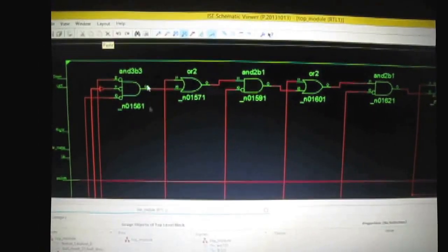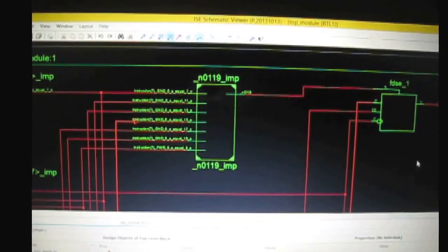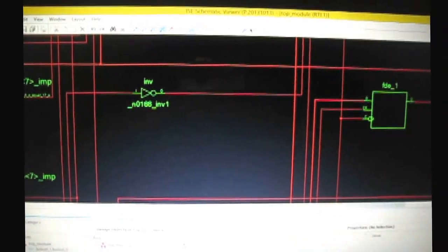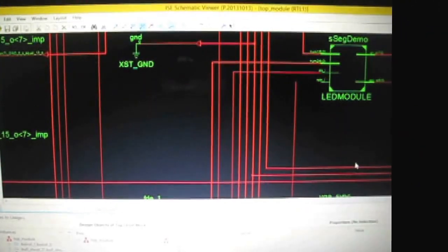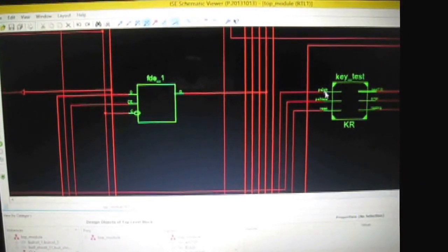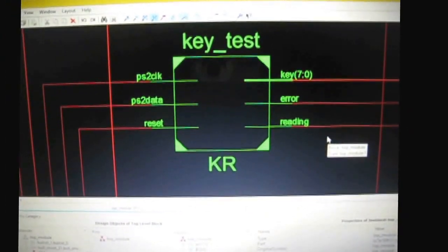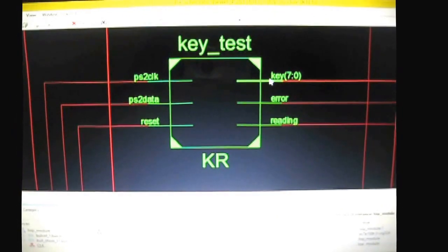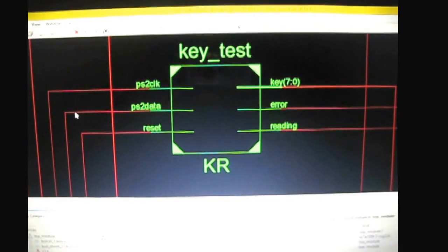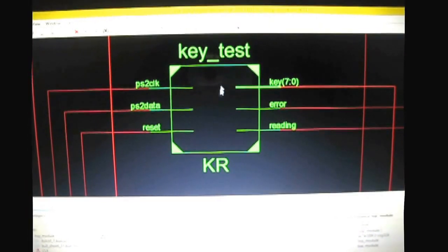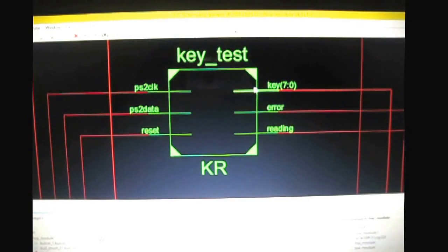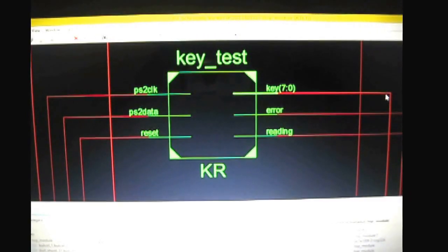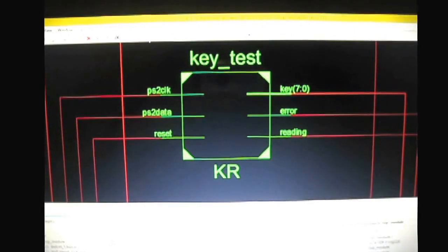So secondly, I want to talk to you about the way the signals coming from the keyboard are acquired by the board. Let me find the right module. Here you can see the module used to acquire the bit sequence and translate it into an actual instruction. So here you can see the single bit entering from the outside, being put together in this module and then being sent to the top module as a set of bits that results in an actual instruction being executed.